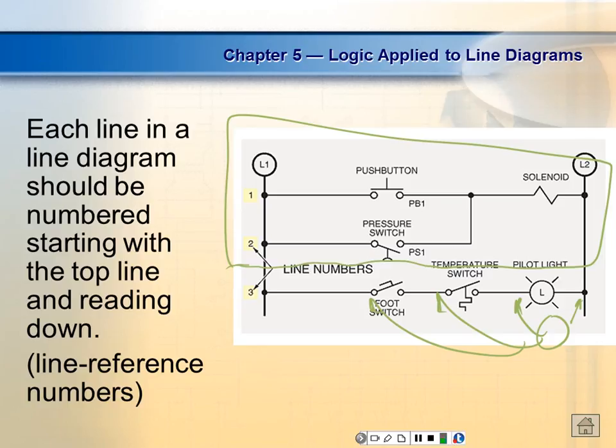At U.S. Steel, everybody carries jumpers. So we have sensors like this. We come over here and measure no voltage there and measure voltage there. It doesn't really mean the switch is bad, because it's not going to close until it sees a certain temperature. So we'd put a jumper across it, and then if we got voltage across our coil and it wasn't activating, that would mean everybody in front of it was what? So two things we carried: we carried lockouts and we carried jumpers. Y'all do that, Earl? Carry them jumpers. Gotta have them jumpers, to jump out these devices that are activated by something.